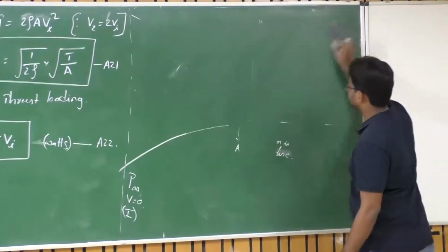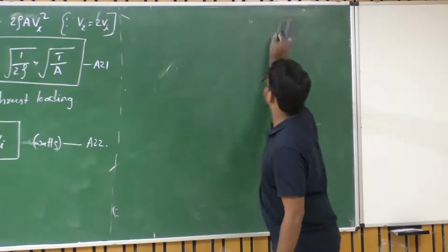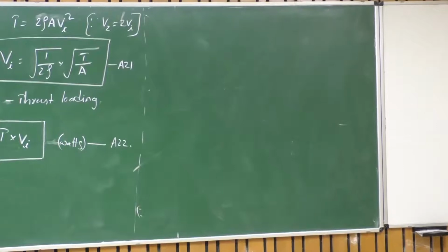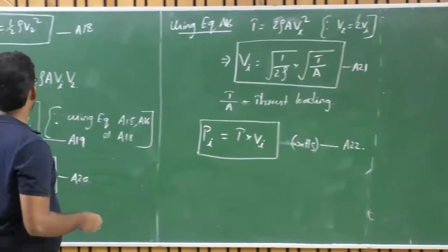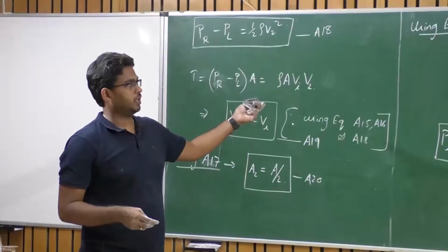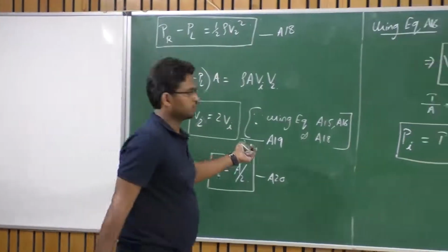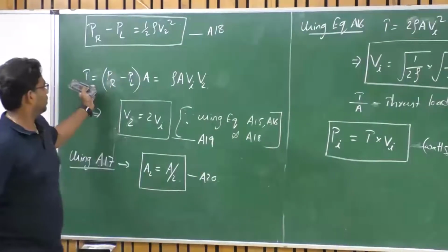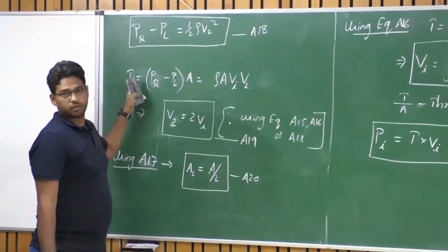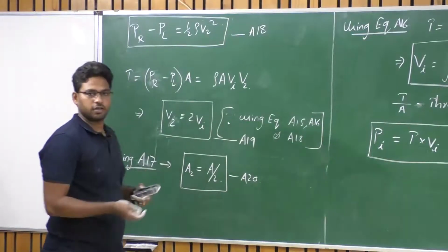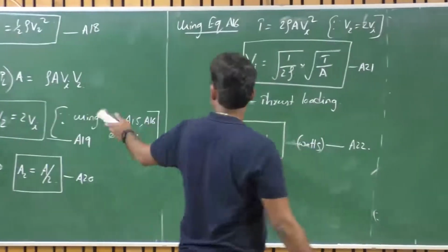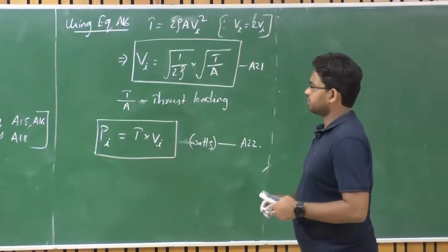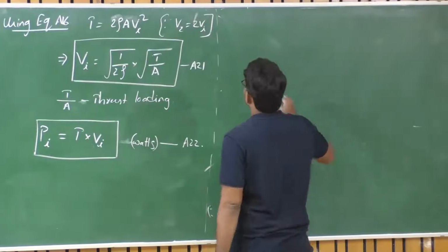non-dimensional analysis or non-dimensional parameters for this particular actuator disk theory, right? With which we will be able to compare propellers of various configurations. So what we are dealing with is Froude's momentum theory or actuator disk theory, right? That is what we are discussing here. So we know now this thrust will propel your aircraft forward, given it overcomes the resisting forces, isn't it? So this is the main idea. This is one of the means with which we can generate T to accelerate our aircraft.